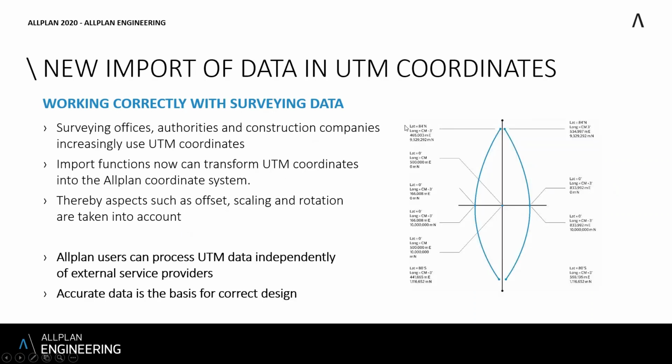And now there's also this UTM, which usually was quite a challenge. So the geodesy specialist engineers, they know the Earth is not flat, so they work with the curvature of the Earth. So when you get a UTM data file describing a terrain, a bigger area of a terrain, then you can get some challenges with the conversion of the coordinates, because usually in design we just draw on a plane.